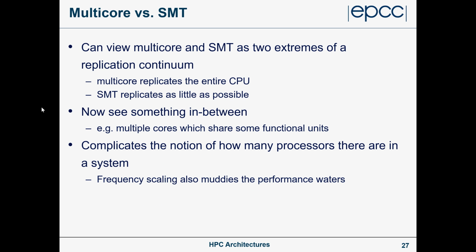So that's really all I wanted to say about processor hardware and processor technology. You can see all these different functionalities that modern processors have as a spectrum of different ways of using the silicon and different ways of hiding memory costs. Multi-core at one end is complete replication of functionality to use more of the silicon, whereas with symmetric multi-threading and hyper-threading, you only replicate small amounts of silicon. And then there's functionality to try and hide memory costs and improve floating point performance. How successful these are really depends on the application you're running and the nature of your code.